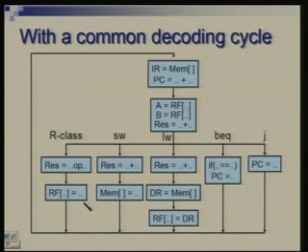Now this is a broader cycle which needs to be repeated over and over again. So after these last states in the chain, we come back to this. As far as the controller is concerned, it is a small finite state machine with about 10 or so states, and it keeps on cycling through these. So here you do the fetch, decode, you come to know what the instruction is, follow one of these paths, and then you are ready for the next instruction. As long as power is on, the processor will keep on going through this.